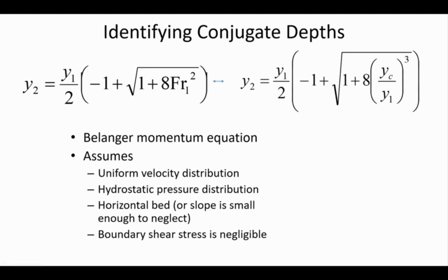The other assumptions are maybe a little bit less flagrant, assuming hydrostatic pressure distribution. Now, hydrostatic pressure applies when the water isn't moving. But since the water is open to the surface, as you go down through the water, the pressure does increase at roughly the same rate as it would if the condition was hydrostatic.